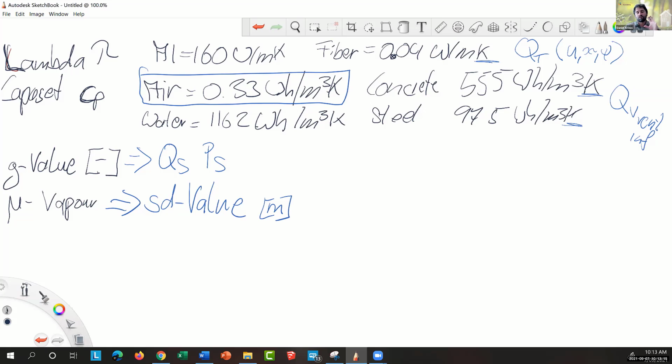All these things you can look at and say, okay, the best return on investment is actually when I buy that glazing, for example, that triple glazing that maybe costs me $5,000 more to go from double to triple glazing. But now I'm saving so much energy over the next 10 years that it has the highest return on investment when I compare it with all the other options, like more thermal insulation in the roof, more thermal insulation in the wall, or a better conditioning system or a better heat recovery ventilation system.